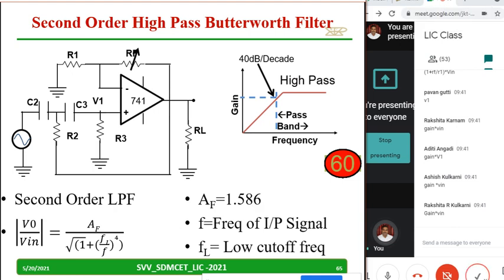This is a second order high pass Butterworth filter. No derivation, directly you can note down V0 by Vin equal to. But remember, AF should be equal to 1.586. This is one important point which you have to remember. So copy down, you can take 1 minute. Only the R and C positions are changed, and the pass band and stop band will now be different. Instead of 20 dB, because it is second order, it is 40 dB per decade. So note down some of the points properly.